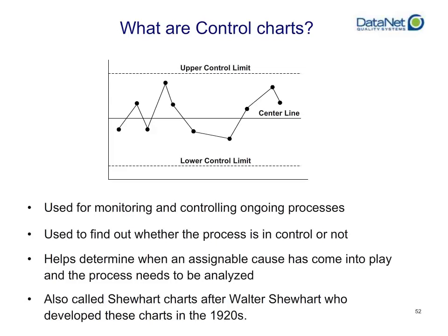The control chart, you're going to find out as you go through this, as you're using the control chart, we would expect nice, healthy, random variation in the outputs of your process. If you are getting anything other than that, if patterns start to show up or something unusual relative to the other data that you've plotted appears, that is cause for investigation, and control charts can be used to pinpoint that, again, hopefully before you've actually started to produce bad product and scrap. Control charts are also known as Shewhart charts, in honor of Walter Shewhart, who developed the charts in the 1920s.